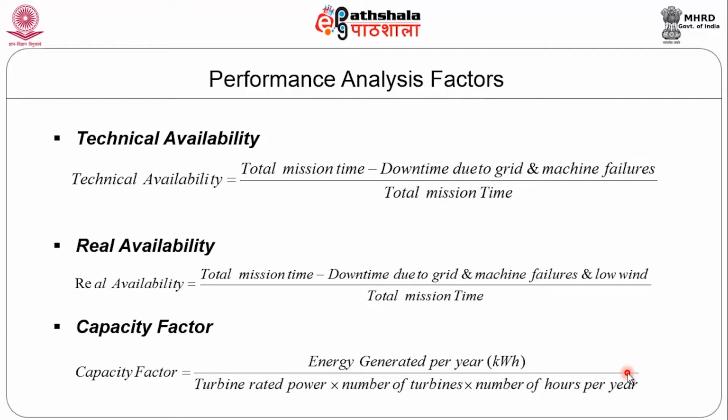And the performance analysis of wind energy system has three very important factors through which we can analyze the performance of the wind turbine generator: the technical availability, the real availability and capacity factor.